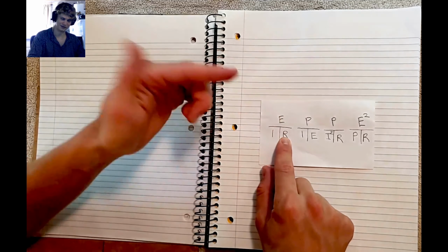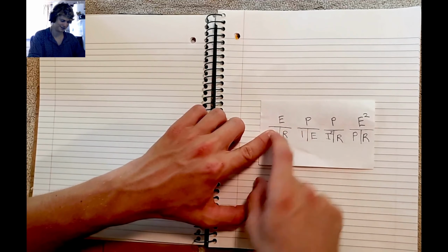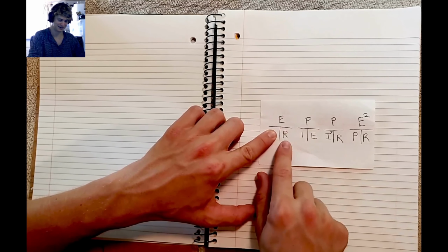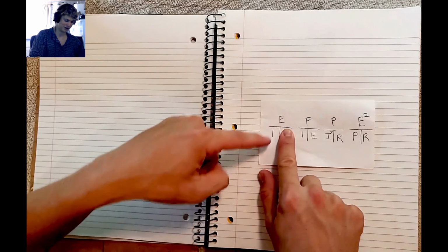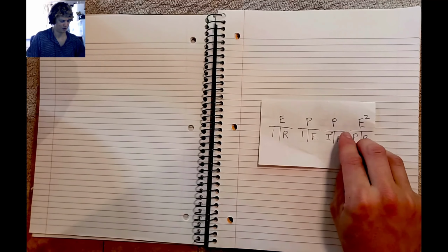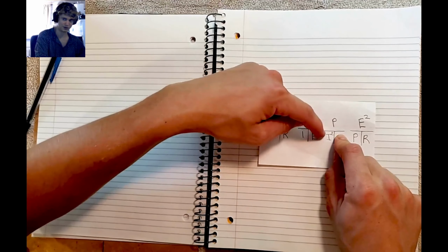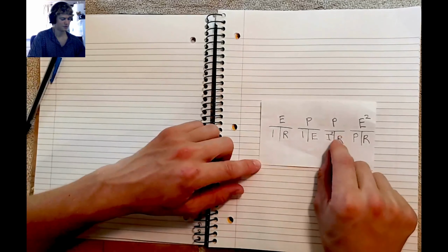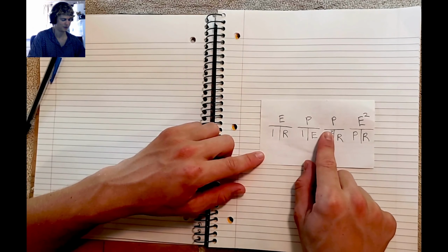And I know I already did this, but I'll go over it one more time. If you cover the I, that's E over R, because anytime that line's there, that's like saying this is over that. If I want to do R, that is E over I, because that's how you do it for all of them. And obviously, let's say I wanted R here, in this case with the square. Okay, that's just P over I squared. It's not too difficult. The weird thing is, what if I wanted to solve for I squared, and that's P over R?